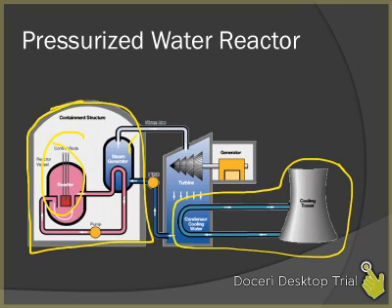If we keep all of that water in our containment lead and concrete, then there's less chance of it escaping. So instead, what it does is the pressurized water, again, is not forming steam. It heats up and heats up and heats up. Then as it heats up, it moves to the right and it comes into our steam generator. Here's just normal water. Okay? Normal water, it's not under pressure, so when it's heated up, it's going to produce steam, right? As it produces steam, it comes up, turns a turbine, turns a generator, and then we try to get it to condense. How do we get it to condense? We need colder water from an area. It's getting pumped in and out and in and out. So basically, we just have 3 loops of water that are continuously moving.